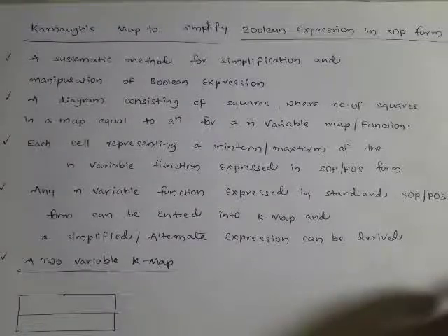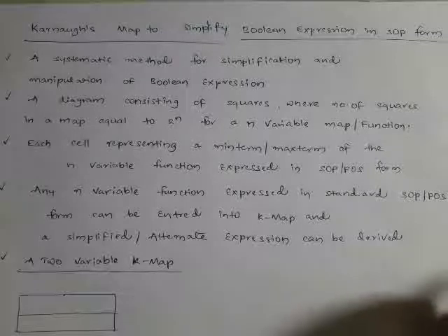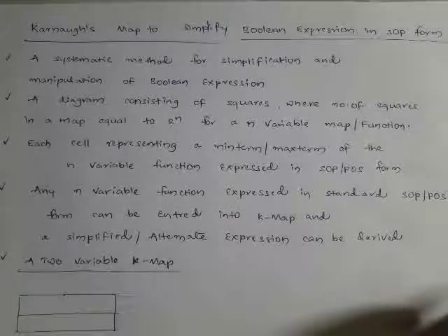If a logic circuit diagram contains a minimal number of logic gates, then the circuit is considered economical. So we'll try to simplify Boolean expressions using the Karnaugh method, which gives us a systematic method for simplification of the Boolean expression.